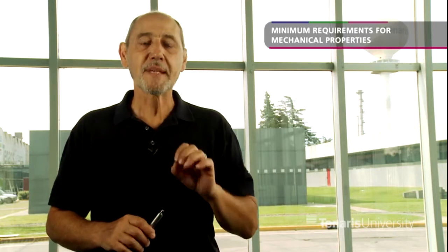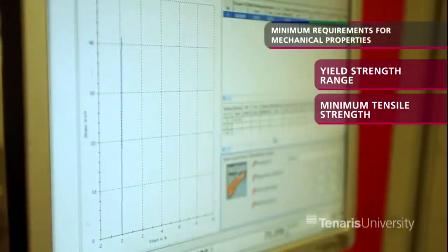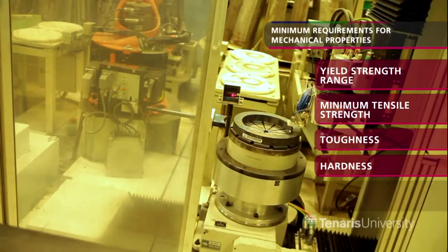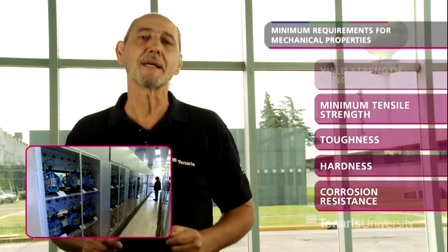Then we have the minimum requirements for mechanical properties. The API 5CT and ISO 11960 standards specify the yield strength range, the minimum tensile strength, the toughness, the hardness, and the corrosion resistance for each one of the steel grades.